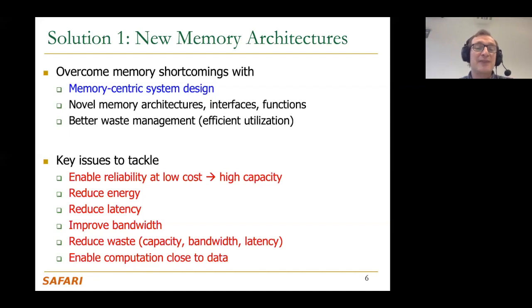If you're doing, let's say, graph traversal, and if you have a lot of random accesses, because you're basically visiting nodes that are connected to each other in some random locations in memory, then essentially you're exercising this bandwidth bottleneck that I just talked about, both at the processor-memory interface as well as inside the memory chip itself. So you're basically transferring 8 kilobytes into the row buffer just to access 8 bytes. And then you're going to get a row conflict, and you're going to open another row, access 8 bytes, and then you keep doing this. So it's a huge waste in terms of both energy and performance.